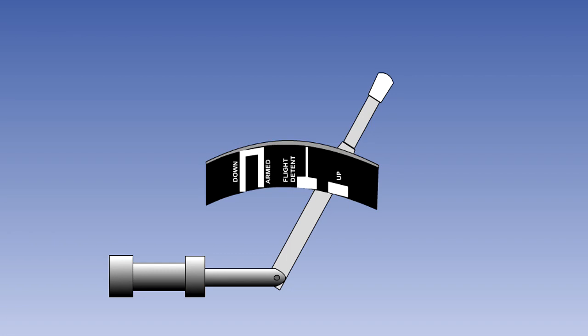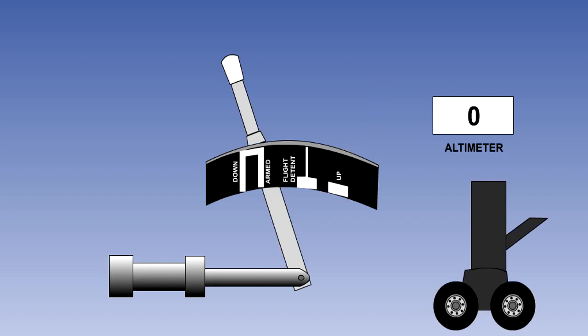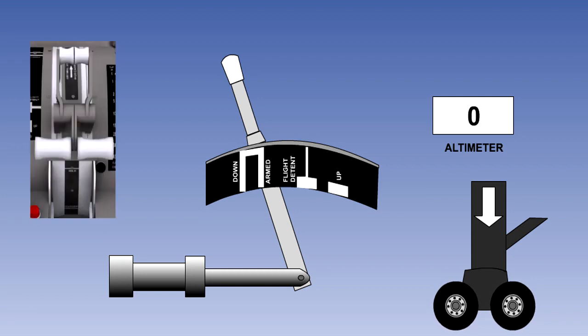Different aircraft types use various different parameters. They will usually include 2 or more of the following: the radio altimeter reading less than 10 feet, the wheel brake anti-skid system sensing wheels spin up, the air ground sensing system giving an on-ground signal, and the thrust levers being fully closed.